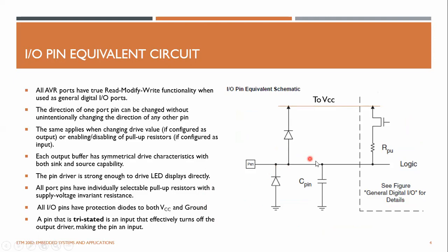And also, if you set it as an output, you can either configure it to drive current or sink current. So when it's set to drive, you can simply drive a simple LED connected to this pin. That is enough to drive a simple LED light.